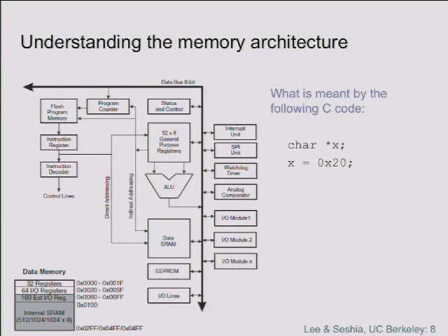Where in RAM? Maybe wherever the stack pointer was. It kind of depends actually on where this code is. Okay, so we need more context. We need to know the rest of the C program to know where in memory this is. Yes, 16-bit address, 8-bit processor. And so the pointer itself is 8 bits. No, the pointer is 16 bits because the pointer is an address.